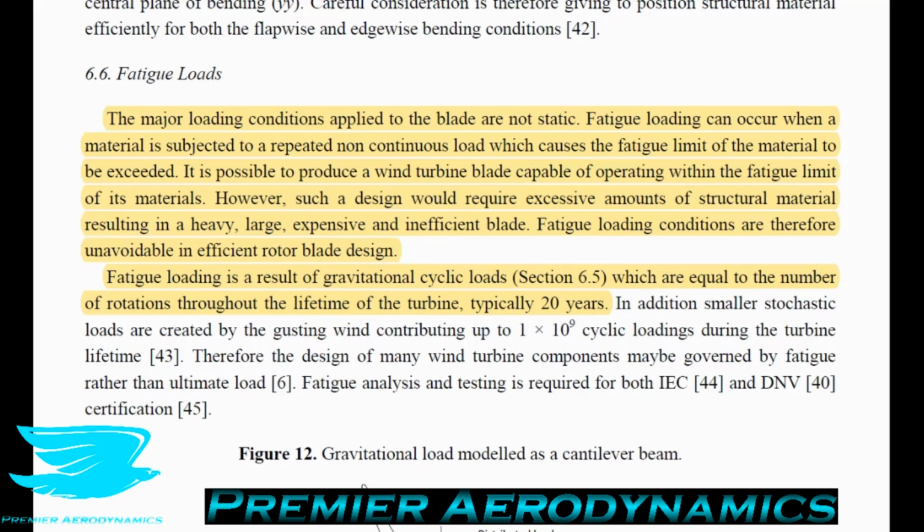Others will get to a point where it just plateaus out, and it doesn't matter whether you load it with a force that is less than that limit, it will never break. For example, mild steel gets to a point where you can load it 1 million times, 10 million times, 1 billion times, whatever. But if you don't exceed a certain force, it will not break.